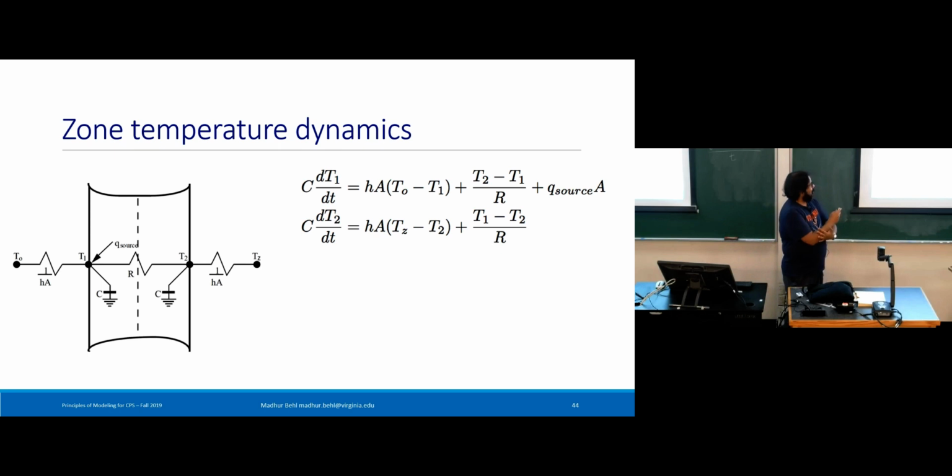Okay. So now the next logical thing to do, if we are good with this modeling of 3R2C, I now propose that in reality, this model is useful to describe the heat flow and dynamics of the external wall or a slab, but this is not really the model we are looking for, because we want to model zone dynamics or zone temperatures. Whereas in this model, the zone temperature T of Z is just a boundary condition to drive the dynamics of T2 and T1. That's the role of this TZ term in this equation.